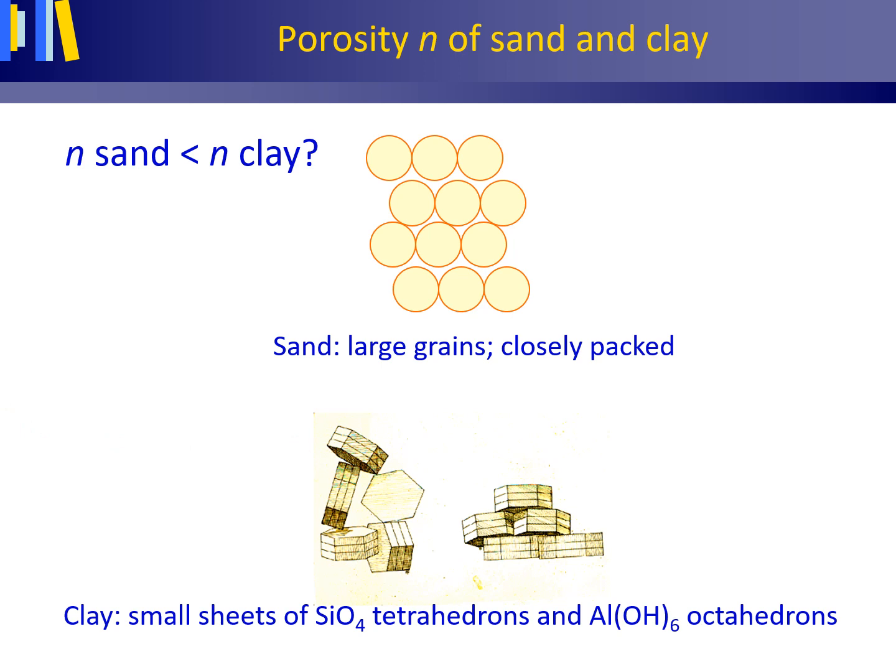The positive news that I can already tell you is that we need not worry too much about the exact forces with which water is bound to the soil matrix in the unsaturated zone, as we have a unifying concept for this, which is the concept of negative pore water pressures in the unsaturated zone when we take the existing air pressure at the water table as a reference or zero level. I will come back to this shortly.